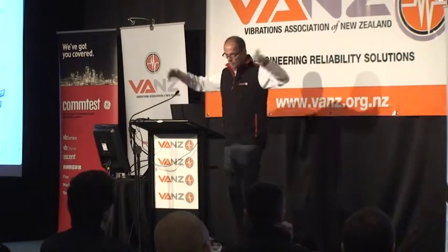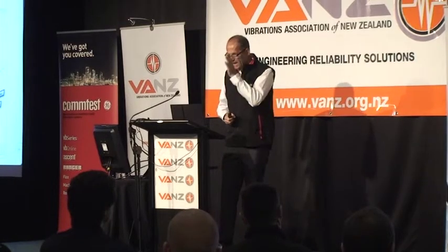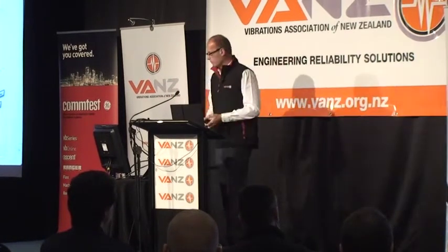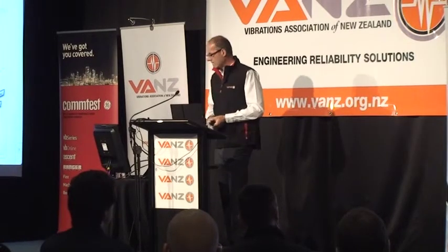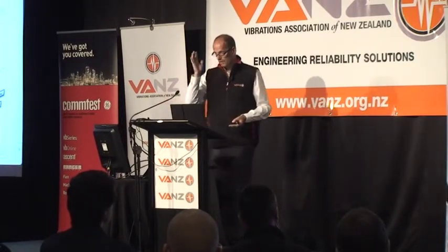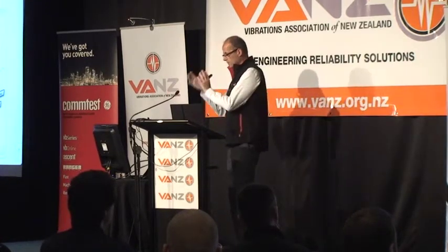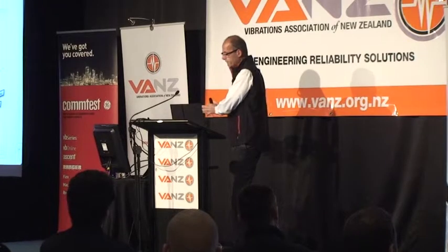That's why, for example, on big steam turbines we have protection systems that are watching every split second, because they can go from happy to destroyed very quickly. On the other hand, with your normal motors and pumps, rolling element bearing failures and that sort of thing, we have more time. But again, we need to use the right technology, use it correctly, and take our measurements frequently enough that we can detect that this failure has begun, and then deal with it.